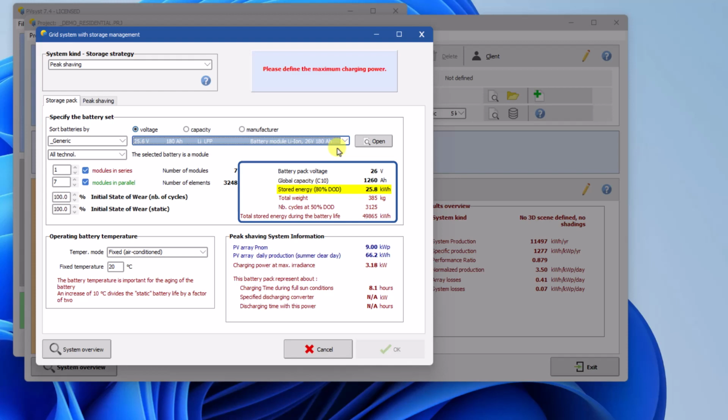This value is indicative for the energy that is stored in a single battery cycle. For lithium-ion batteries, the charging cycle should never be 100% DOD, since a deep discharge or an overcharge reduces the battery lifetime or can even cause irreversible damage. The total weight is also displayed for information, to give a rough idea of the physical size of the battery.